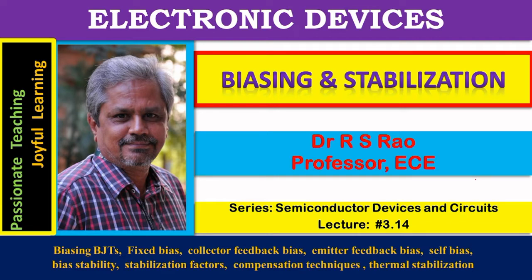If we want amplification from a BJT, we have to operate it in active mode. Emitter junction under forward bias, collector junction under reverse bias. These biases are provided by the biasing circuit. The bias circuit is mainly meant for establishing the operating point at a proper location.